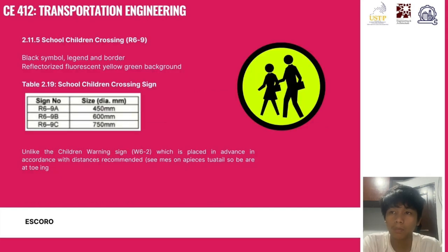So for 2.11.5, the school children crossing, the R69 sign, it has the black symbol, legend and border, a reflectorized fluorescent yellow-green background. You can see here the table. And unlike the children's warning sign, which is placed in advance in accordance with the distance recommended.